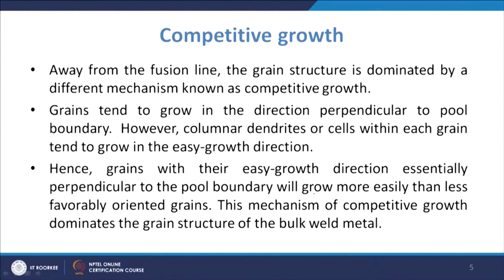Normally, when we talk about the grain structure near the fusion line, away from the fusion line the grain structure will be dominated by a different mechanism known as competitive growth.